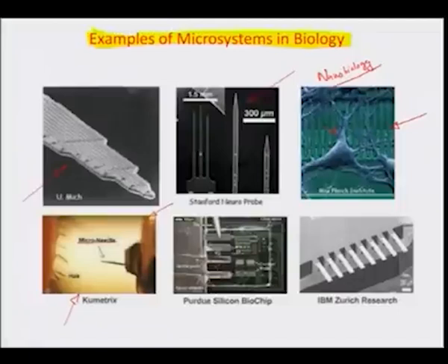But otherwise these needles are about 20 microns in diameter and about 180 or 200 microns in length. So it is a high aspect ratio, slender structure, and such structures, if we can fabricate them as arrays or groups over, let's say, pads which can be mounted on the fingers or different regions of the body, you can think of or envision a system of painless drug delivery to the human body.